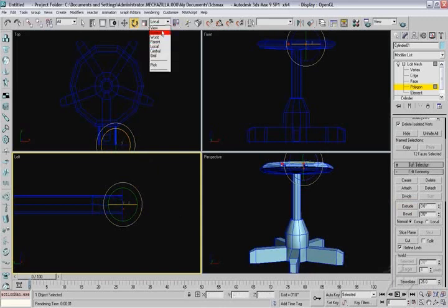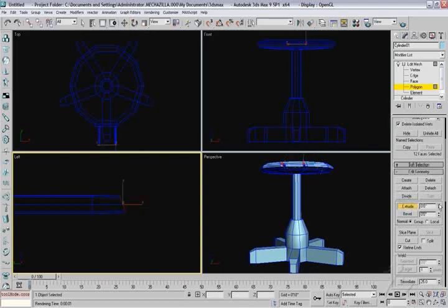I want to switch that to a view coordinate, and grab that outer band and rotate those at a slight angle, probably about 45 degrees. And then I want to use my extrude tool, and I'll use the rollout again and extrude just a little bit and stop, and right click in my viewport again, grabbing that band and rotating it another 45 or so. It should take about 3 bends to make it around the corner.